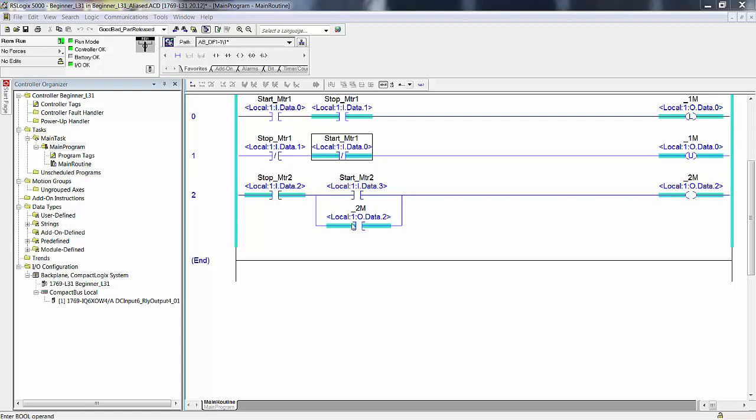This contact right here is part of that coil. So if this were a relay, you'd call this relay CR2, control relay 2. This would be CR2-1. It would be a contact that's mechanically connected to this coil. You push the start button, it energizes this coil, closes this contact. So now you have current flowing through both of these contacts to this relay coil. When you let go of the push button, it continues to flow through its own contact. It is self-sealing. It is sealing logic.